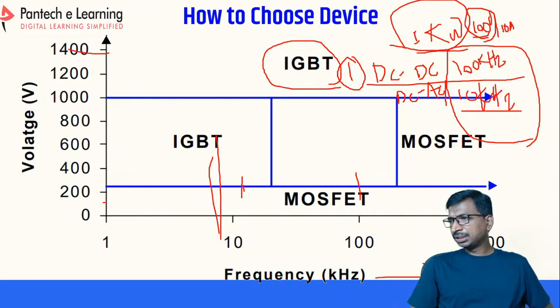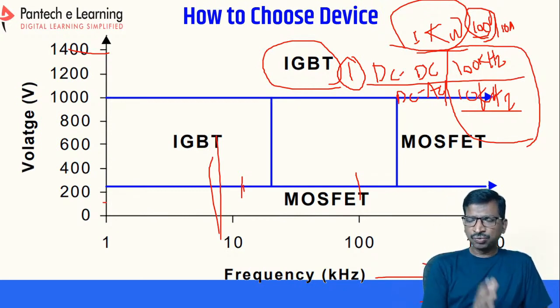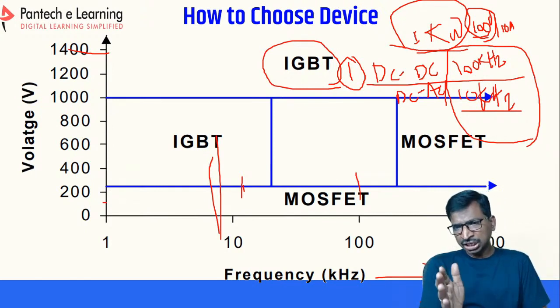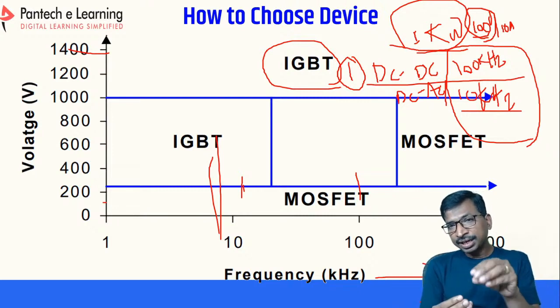Fast switching damages the MOSFETs. That's why I am asking how to control the switching. See here, the PWM will not damage your MOSFETs if you are choosing the proper MOSFET based on the data sheets, you can check the data. The PWM will not damage your MOSFET unless you are generating a wrong PWM.